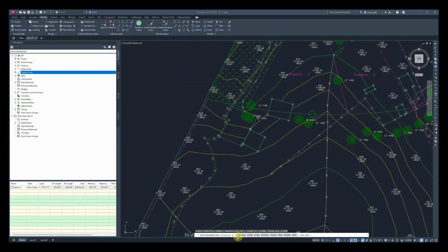What you do see is we have the option to edit all of these specific features of our line, these specific parameters. We also have a quick pop-up here. It's giving us the information that we currently have, what the station identifier is, what our grade in and grade outs are, and again, these are our options for editing it. So we can, by default, change the elevation, which we have it currently identified as 184.584. That can be changed without inputting an additional parameter, or again, you do another parameter to do it.